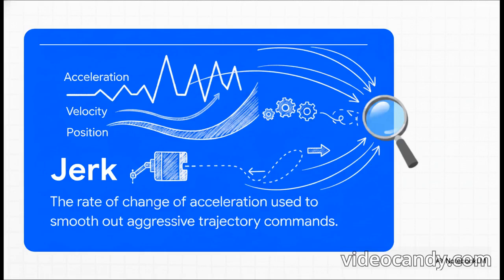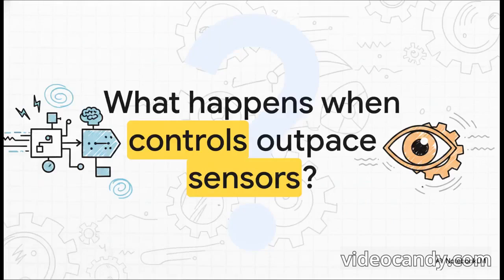To squeeze out that last drop of performance past the stability limit, we use our final tuning weapon, jerk. Jerk is quite literally the rate of change of acceleration. If your tuning hits a strict stability wall but the system is still experiencing following errors, you can inject massive jerk values into the motion profile. This smooths out the harsh beginnings and ends of the acceleration curves, heavily reducing peak following errors without sacrificing one bit of the control loop's overall bandwidth.